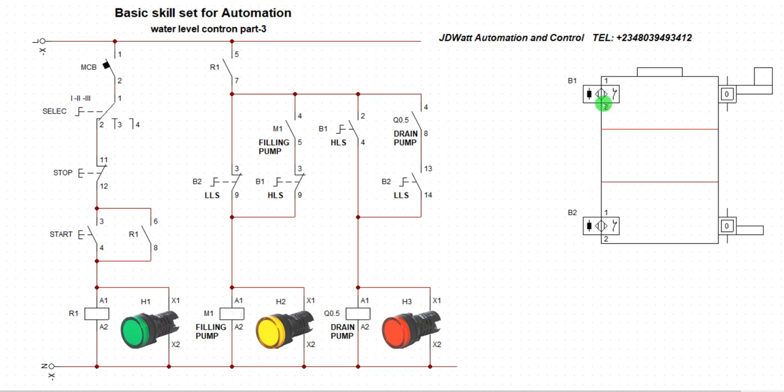So this is what you do. You install this water sensor at the set maximum level, and you also install one at your minimum set level. This is the minimum and this is the maximum set point. You install them respectively. Then this is the discharge pump and this is the inlet pump, which pumps water to the tank through this inlet.